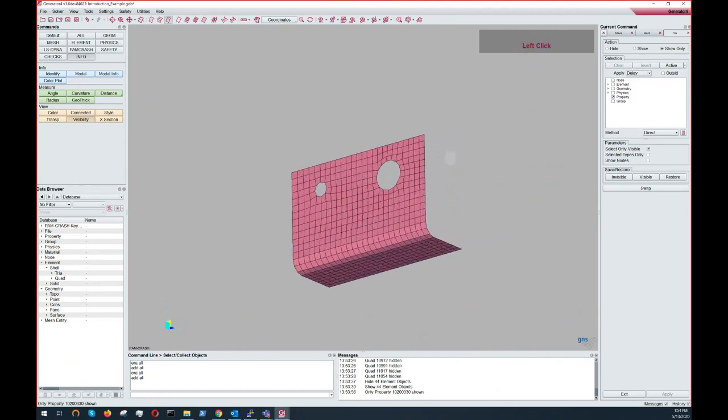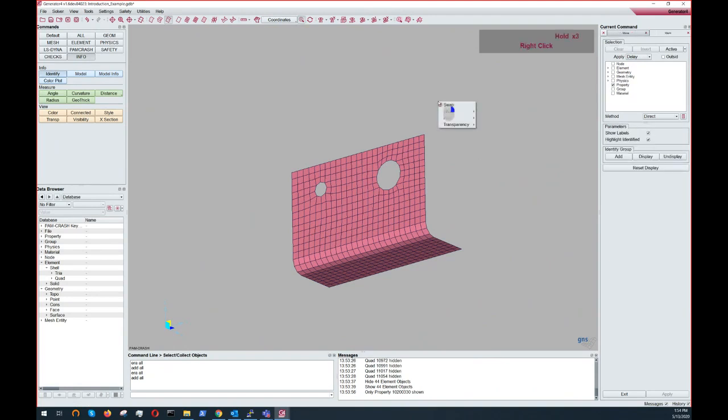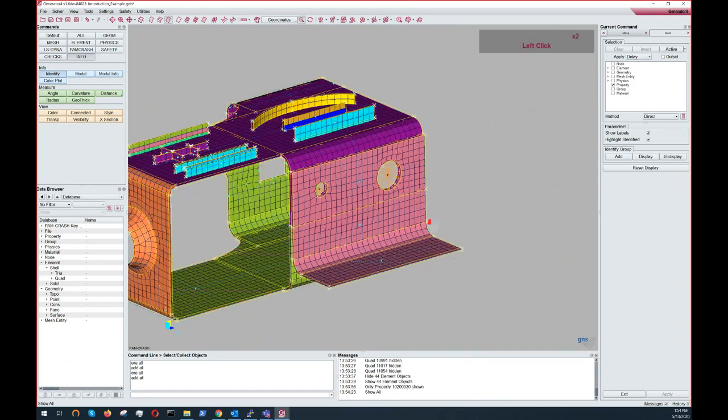There is a fourth option to handle the visibility, and that is accessible with right mouse. If you keep the right mouse pressed a little bit, then you get some extra options here, and it's quite like Animator. So you can show all or hide in some box or wherever.